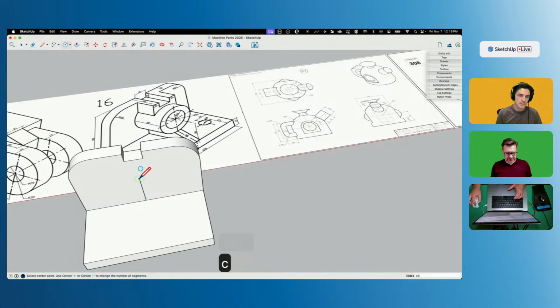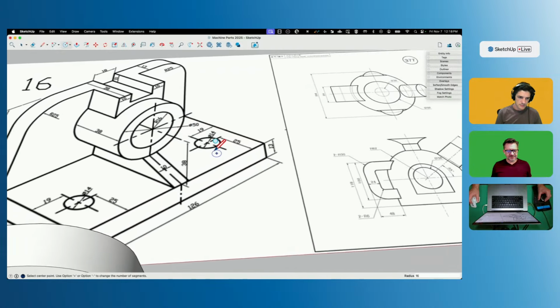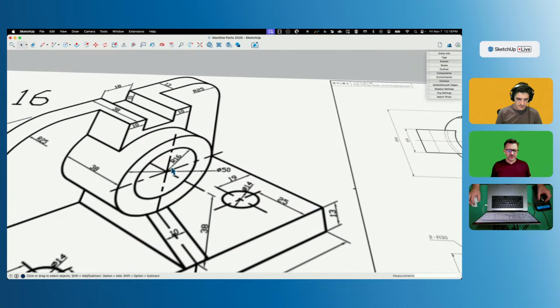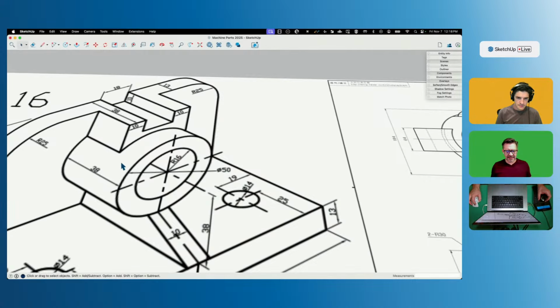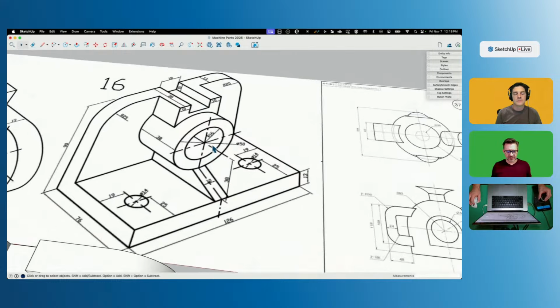And then I will put a new circle in, still 48 sides, so it keeps my last circle size. That's a radius of 16, so I'll come down 16. There we go. Then I have an outer one that has a circumference of 50. You notice that this is kind of cool. I like when they do this. This one has a radius called out. This one has a circumference called out. So you have to be careful when you're modeling to make sure you pick the right one.